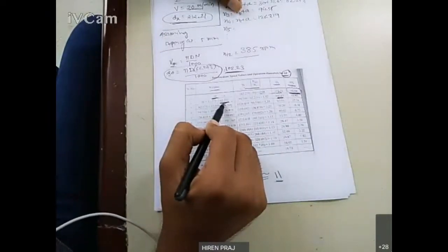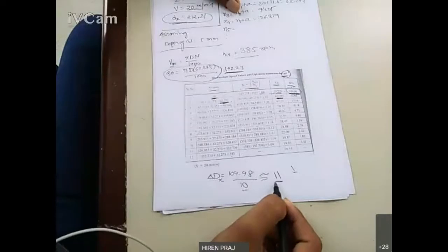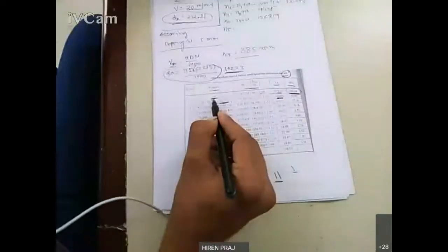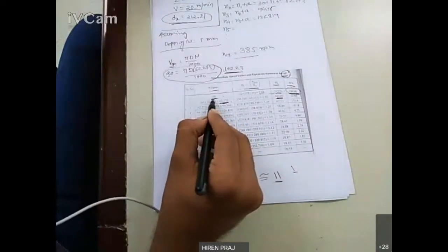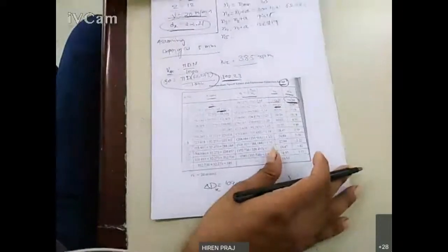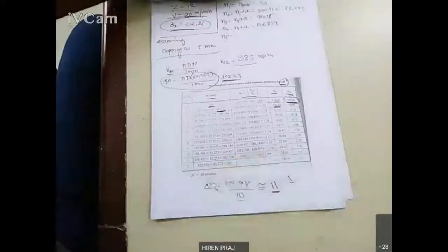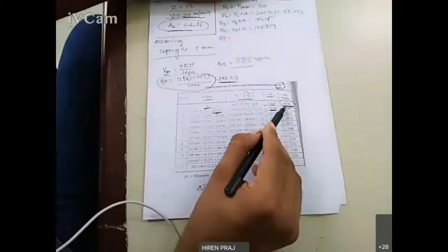Only your first pass, the initial pass, is economical. The remaining 10 passes are not economical, because in those passes you are removing material with RPM 30 and you are not achieving your required optimum cutting speed. So that is uneconomical. So 10 passes are uneconomical if you are using arithmetic progression series.